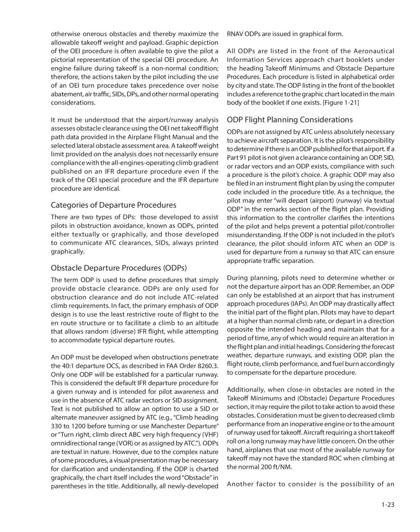If a Part 91 pilot is not given a clearance containing an ODP, SID, or radar vectors and an ODP exists, compliance with such a procedure is the pilot's choice. A graphic ODP may also be filed in an instrument flight plan by using the computer code included in the procedure title. As a technique, the pilot may enter "will depart, airport, runway," via textual ODP in the remarks section